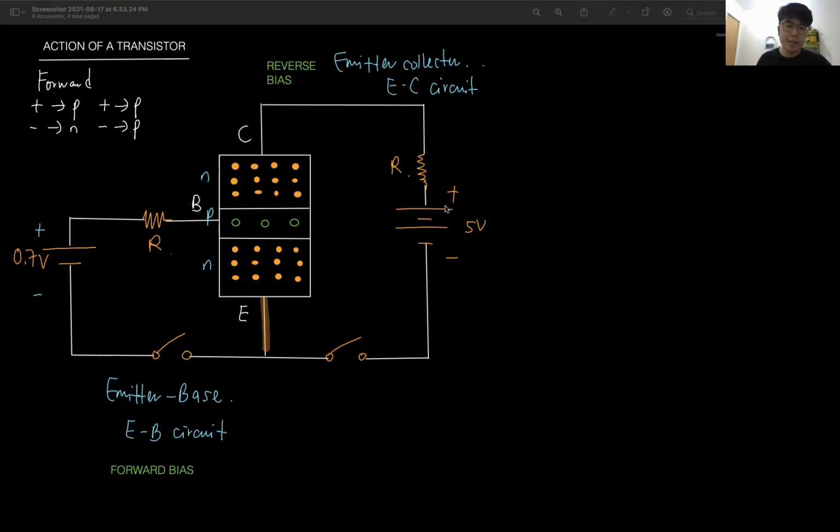Okay, they give you the circuit here, they change the terminal. They say, is this connection correct? So you check, the emitter base must be forward, the emitter collector must be reverse bias. Always, okay? That's the first thing. Now let's see next. This is reverse bias, right?